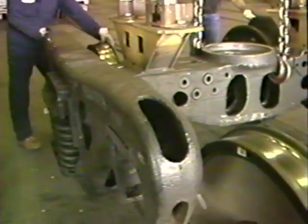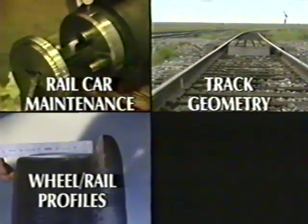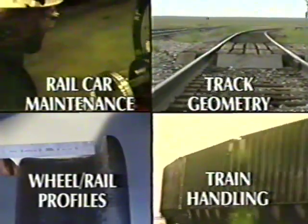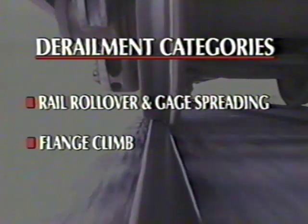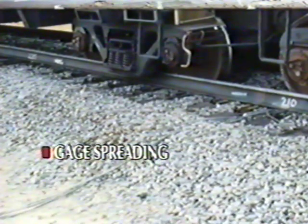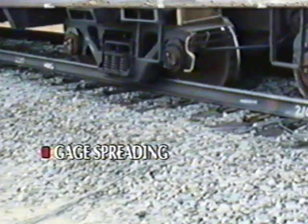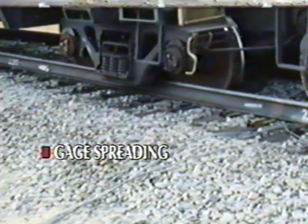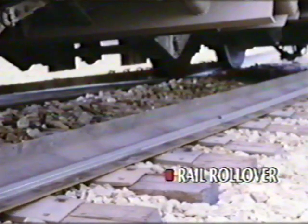Factors that contribute to a derailment include rail car maintenance, track geometry, wheel-rail profiles, and train handling. There are two general types of vehicle-track interaction derailments: rail rollover and gauge spreading derailments, and flange climb derailments. Rail rollover and gauge spreading derailments usually involve loaded cars that generate large forces which act to spread the rails apart until the wheels drop between them, or the force causes the rail to actually roll over, causing a derailment.